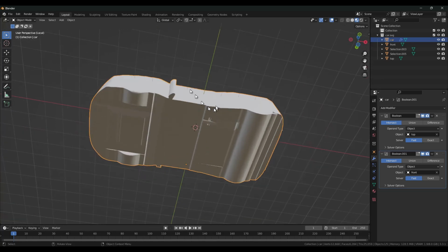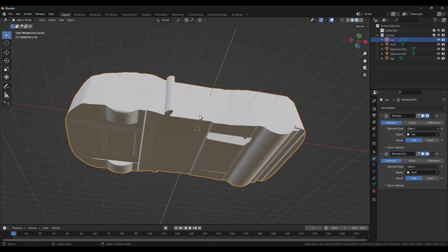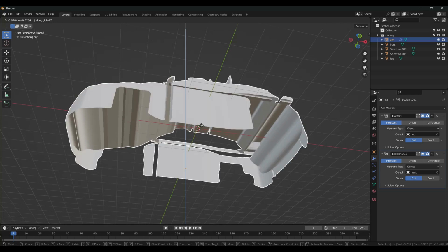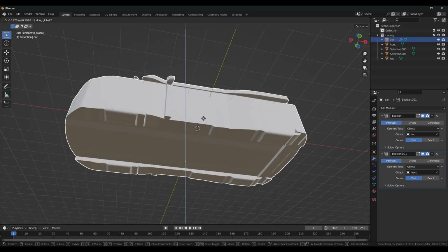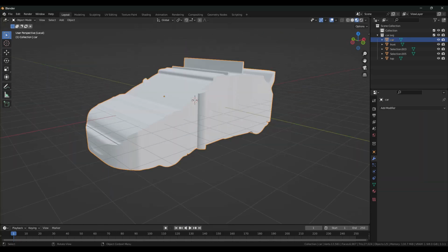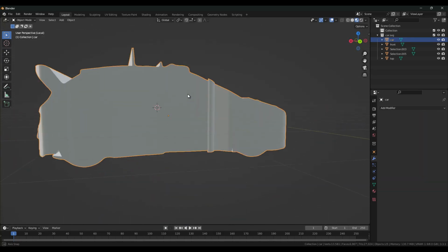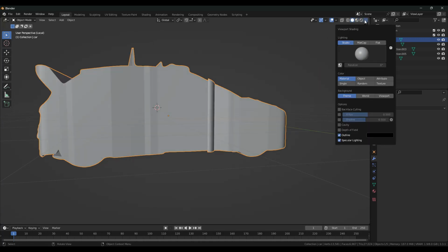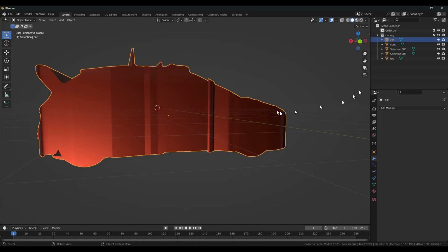It's got errors, like there's a hole here, but then you just grab the mesh and you move it. In this case, I'm just moving it up and down the Z-axis until it's perfect. There are no holes anymore. Once I'm satisfied with that, that's it. It's done. You apply the booleans, and there you go. There you have it.